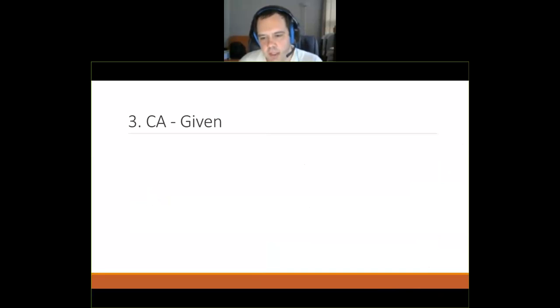All right, then we need to know what our coarse aggregate is, and I gave that to you in the problem statement. We said that it's going to have a 1.5-inch max and a 1-inch nominal max. Very important to note that these are different, so we want to make sure that we keep these straight when we are making our selections.